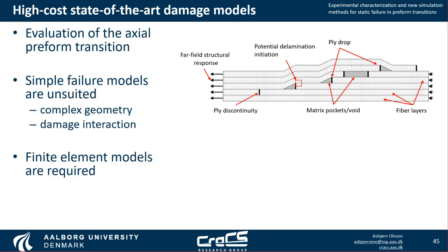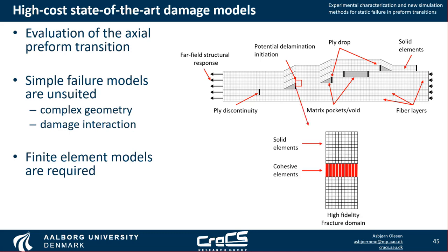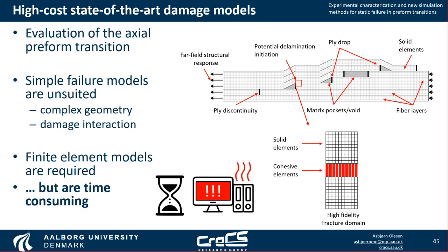To solve these models, we need finite element models, and these need to be finely discretized solid element models using cohesive elements to capture delamination damage. The issue here is, however, that these are time consuming, and therefore they are difficult to use in a design context because you cannot design a laminate and then have to wait a week, 2 weeks maybe before you see the results and then change your design.